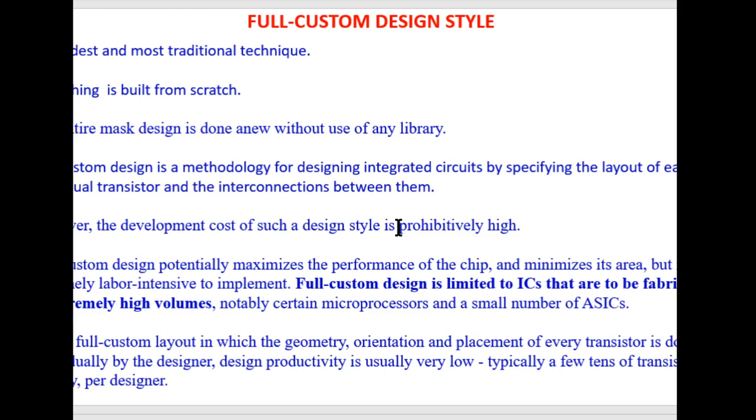So if it gives us a very high development cost, then what is the use of this VLSI design style? The use is this: since all the components are built from scratch, from the very initial phase, we have full control over the performance of each of those components. It means that each of those components, designed from the very initial phase, can be optimized according to our need.